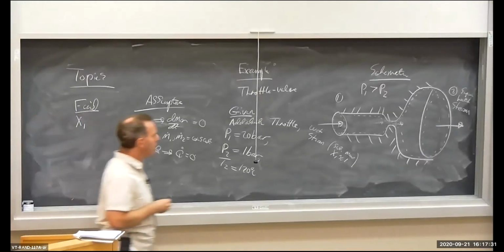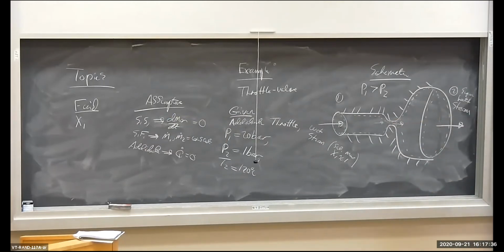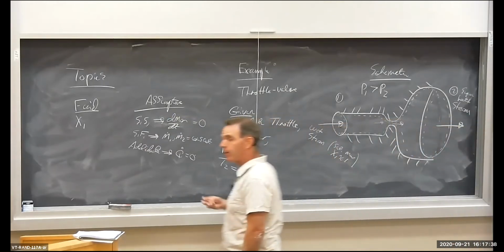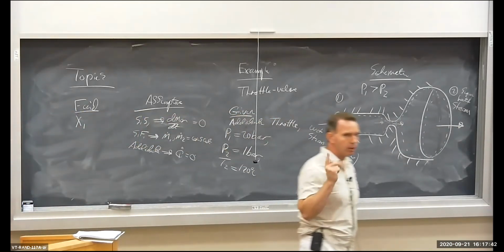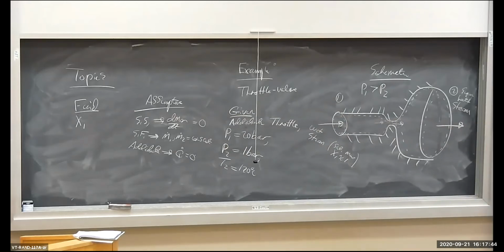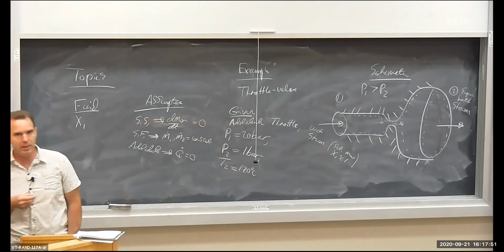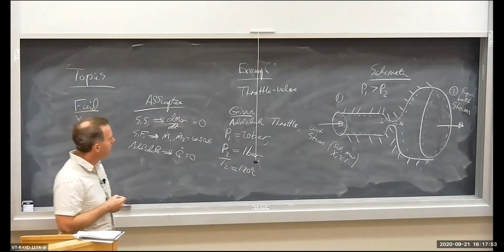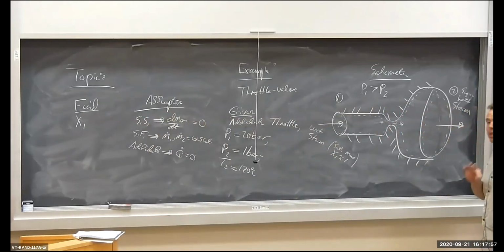What about W dot, the work term? Remember, in the open system energy balance, W dot has 3 components: boundary, shaft, and electric. The pressure power has been absorbed into the enthalpy term in the m dot terms. The U became an H. So let's ask ourselves, is there any kind of work going on here, with the exclusion of pressure power or pressure work? We don't have to worry about that.